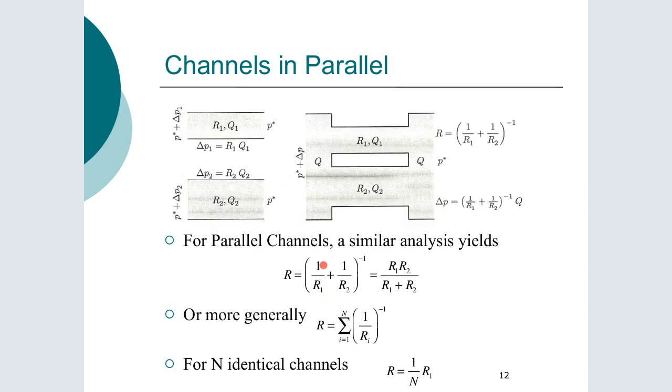The other scenario we have, and it's more typical, is that we'd have channels in parallel. So again, this is a typical way in microfluidic systems of increasing your yield. So you would put an awful lot of channels in parallel and multiplex your system. And then what you have is a manifolding issue where you're trying to distribute flow evenly down each of the channels. So getting good balance between your resistances becomes very important. So making sure they're the same length, and the cross-sectional dimensions have very tight tolerances will ensure that you have a good distribution of flow.